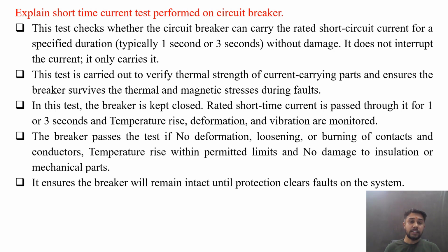In this test, the breaker is kept closed, rated short time current is passed through it for 1 or 3 seconds, and temperature rise, deformation and vibration are monitored. The breaker passes the test if no deformation, loosening or burning of contacts and conductors, temperature rise within the permitted or specified limits, and no damage to insulation or mechanical parts occur.